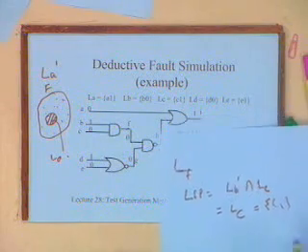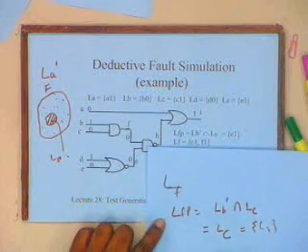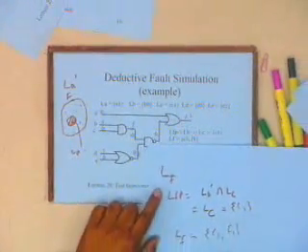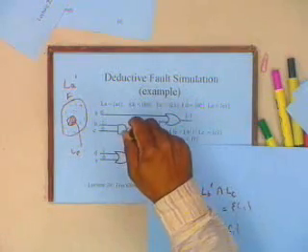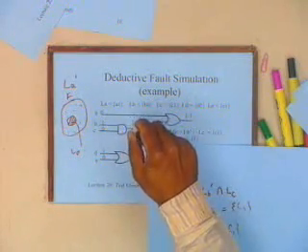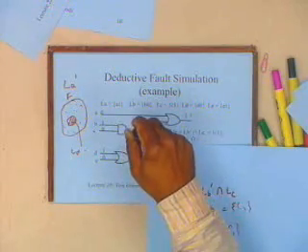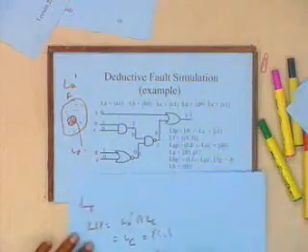So I get LF propagate, and then I get LF. LF is what is propagated plus what gets generated here, and in this case it is C1, F1. These are the faults that can possibly be detected at node F: some faults which get propagated and some fault which gets generated over here. Now let us look at the next case, which is LGP.